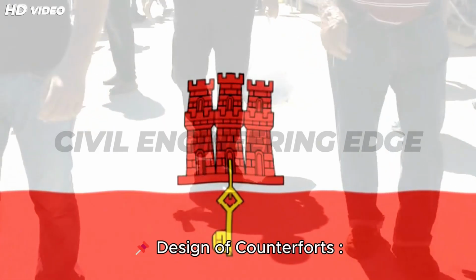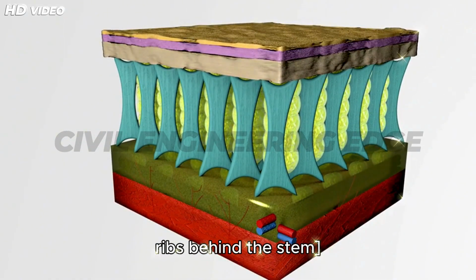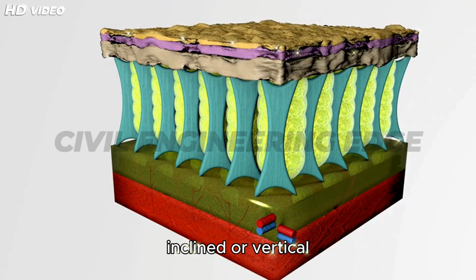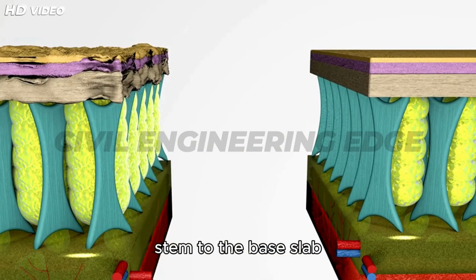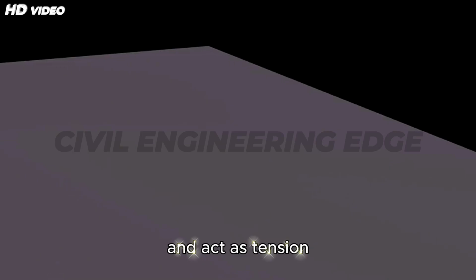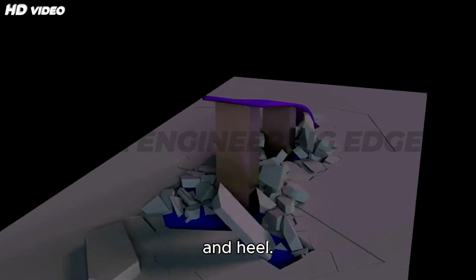Design of counterforts. Scene: internal 3D view of counterfort ribs behind the stem. Counterforts are inclined or vertical reinforced concrete ribs that connect the stem to the base slab and act as tension ties, reducing bending moments in the stem and heel.